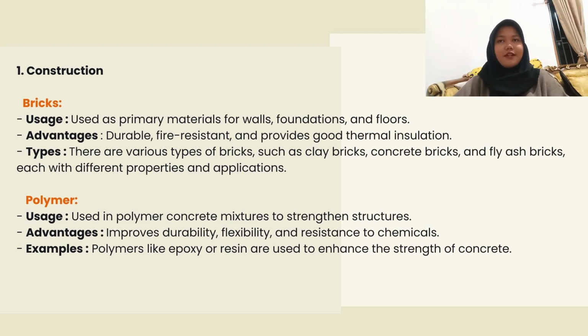For construction, first, bricks. Usage: used as primary materials for walls, foundations, and floors. Advantage: durable, fire resistant, and provides good thermal insulation. Types: there are various types of bricks, such as clay bricks, concrete bricks, and fly ash bricks, each with different properties and applications.